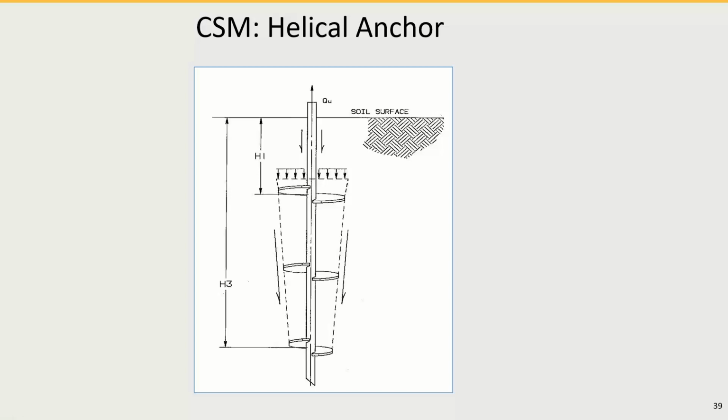almost any helical pile manufacturer I've seen has what you call 3D spacing. What does 3D spacing mean? That means D is the diameter of the lower helix. Let's say this is an 8-inch, 10-inch, 12-inch helix configuration. If 8 is the bottom one, you multiply 8 inches by 3. That's 24 inches. So this 10-inch is 24 inches from the lower one.